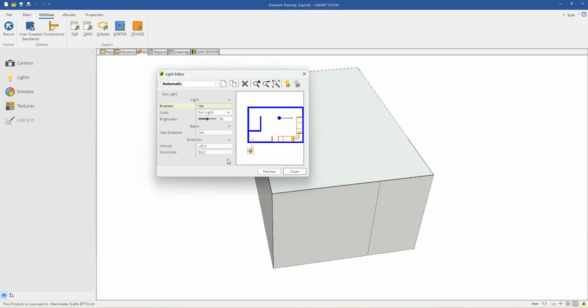And how do I move the light? You can't move the light at all. You can just change the angle. Where you change the angle is here on the left, on the bottom, direction, vertical and horizontal. Great. Because remember, with the sunlight, it's not just a single light that shows in that direction. So it's basically north facing now. That will be north facing, yes.